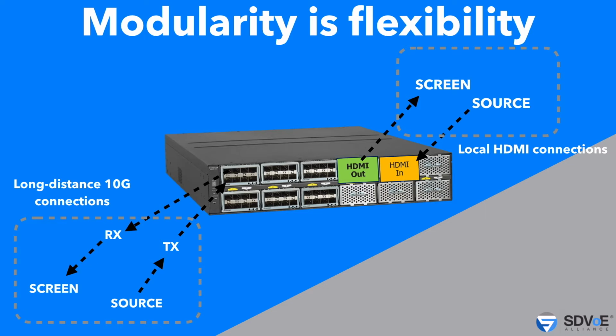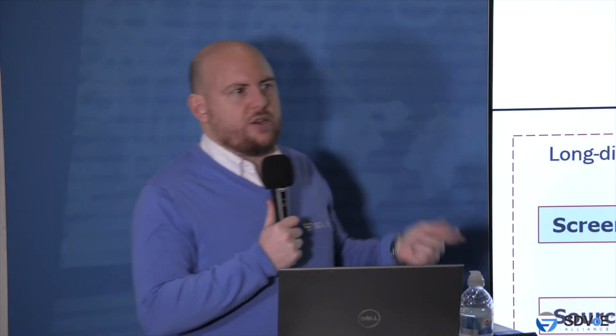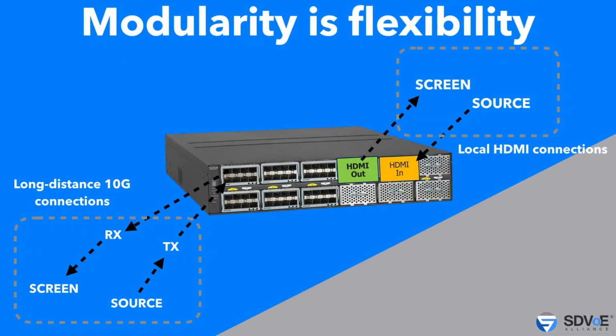AV over IP before now has been disadvantaged by that because when you have local sources to the switch, maybe you've got a bank of PCs or a codec farm in the rack, or you've got cable TV boxes in the rack. With a matrix switch, you put in an HDMI card, you connect those sources right to the switch, and off you go. With traditional AV over IP, of course, that cable TV box has to plug into an AV over IP encoder, which then plugs into the switch. You've got an extra device, extra power supplies, extra stuff in the rack.